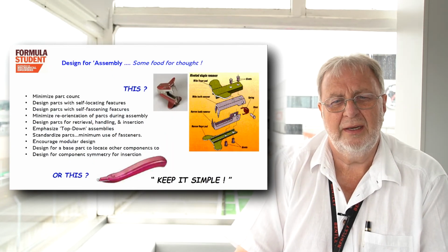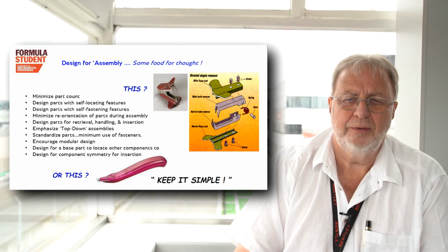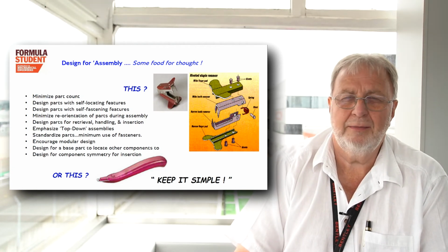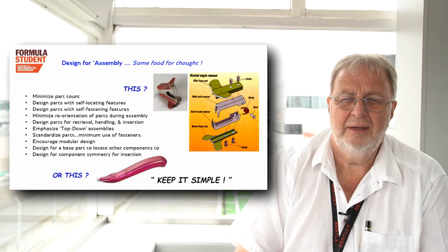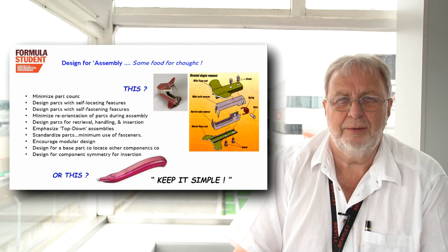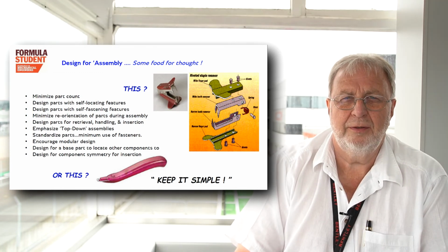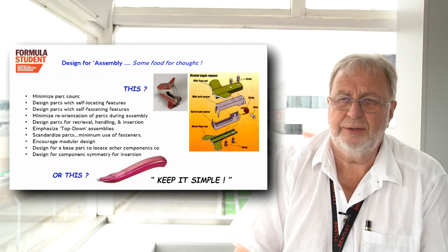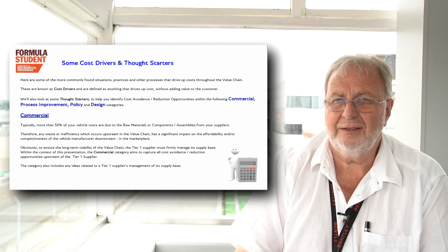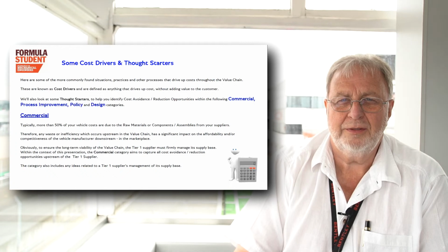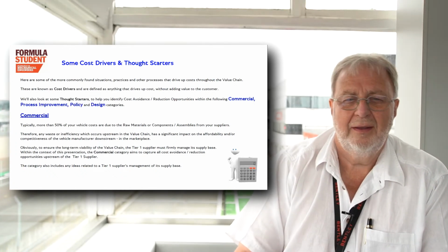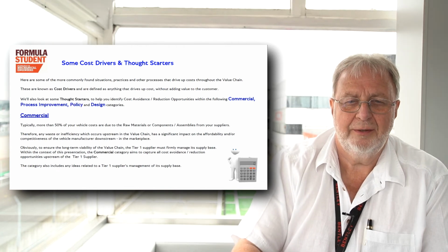An example I'm showing here is a simple staple remover. The standard staple remover that you'll all probably have on your desks is made up of about 10-12 parts, a mixture of metals and plastics. There's many more simple options available to you, and I've just shown another example here with a simple blade that's encapsulated in plastic. Does exactly the same job, same performance, but think of the assembly that you're saving. It's worth thinking about.